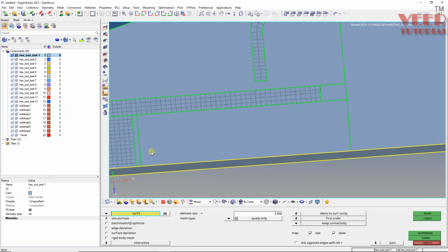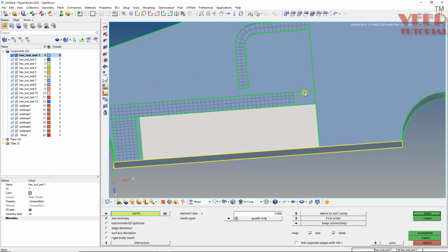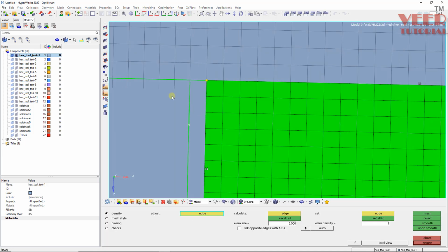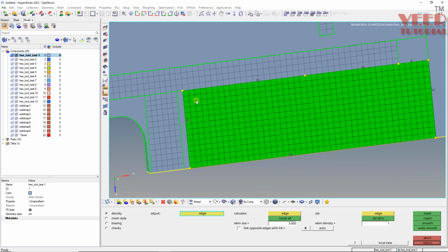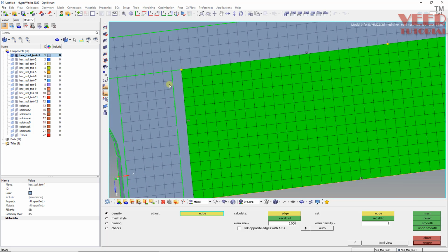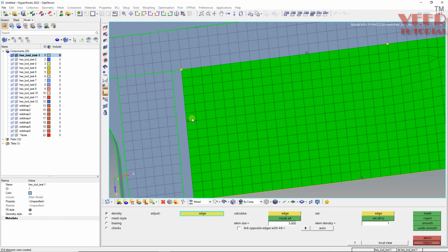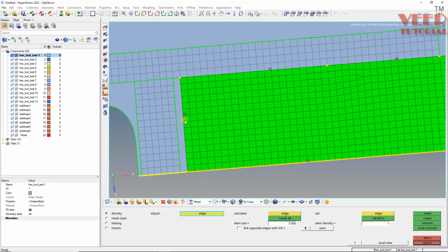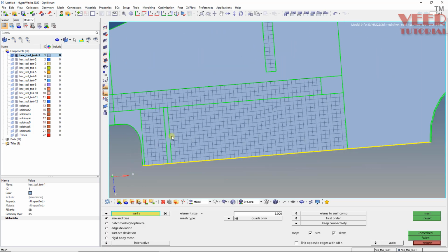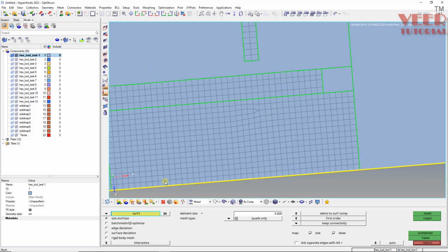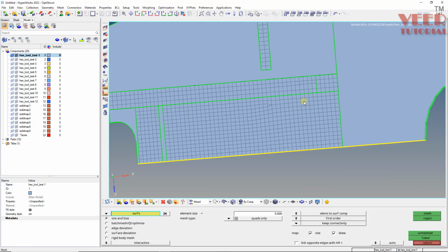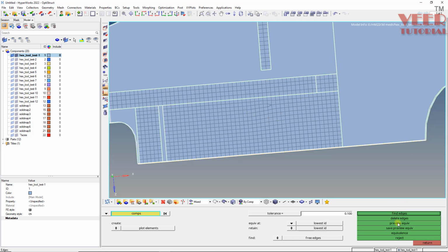Okay, and I will do a basic mesh here, just to make sure that the count of this element should be proper. So you can see here, let's say I will increase the count here. So this should look fine. Okay, this tria, we will change this later, and like this. Then we can preview equivalence and equivalence.